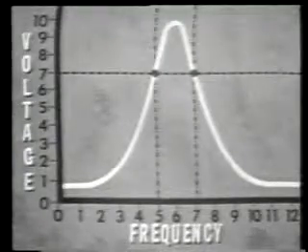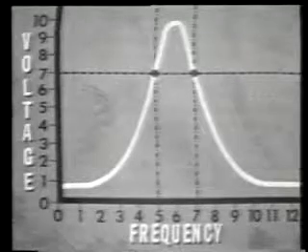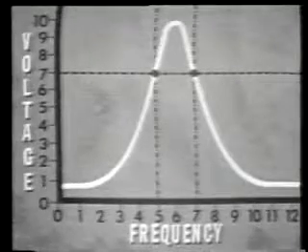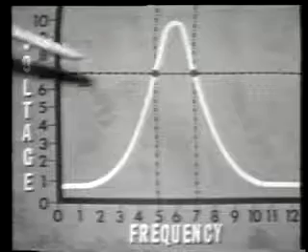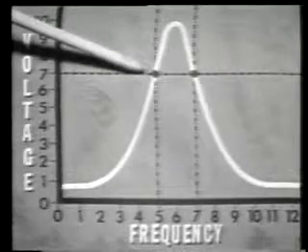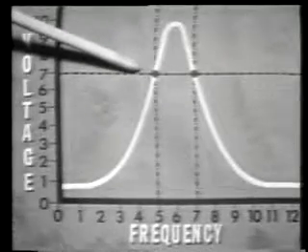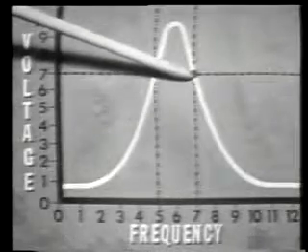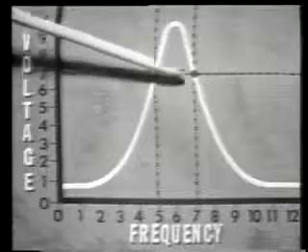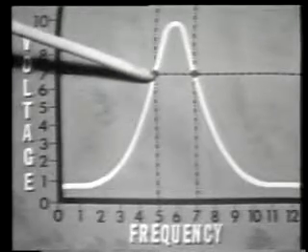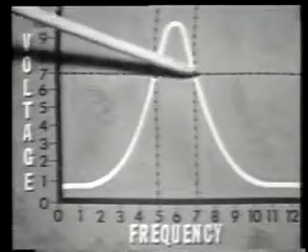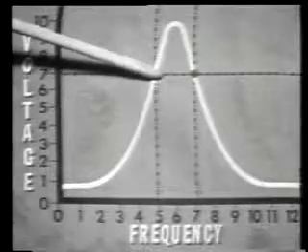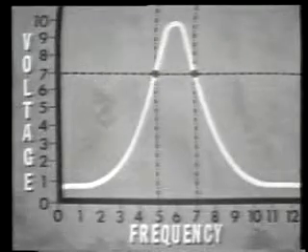Now on a graph, you can see that at about 500 hertz, the output voltage is 7 volts. And again, at about 700 hertz, the output drops back to 7 volts. So in between these two frequencies, we have usable output from the filter between 500 and 700 hertz.